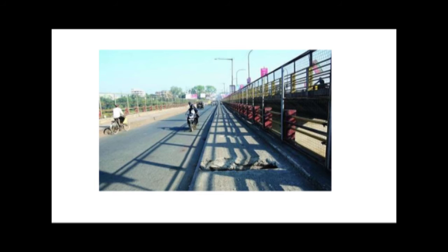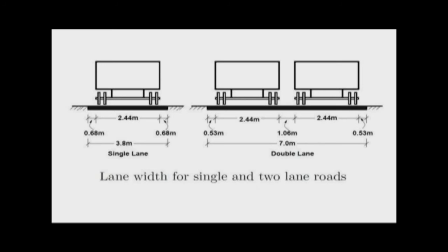I can quote an example here. If one walks over a footbridge, there are numerous cavities or holes provided at the edge or the periphery of the bridge on either side, and one may notice that it is actually for drainage purposes. It is actually to divert water, and there's a very slight, very mild slope provided on the surface of the footbridge, and it's for every bridge. You will easily see a proper hole in the footpath or on the deck slab surface, which takes the water down. Then we have the approach slab.